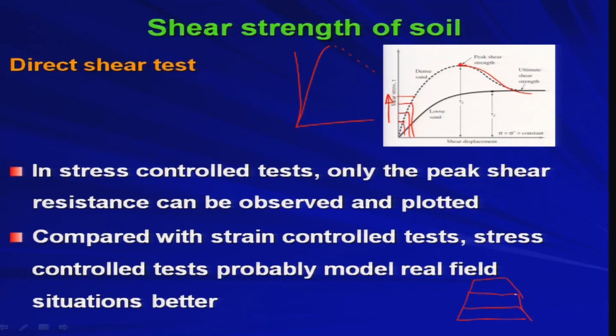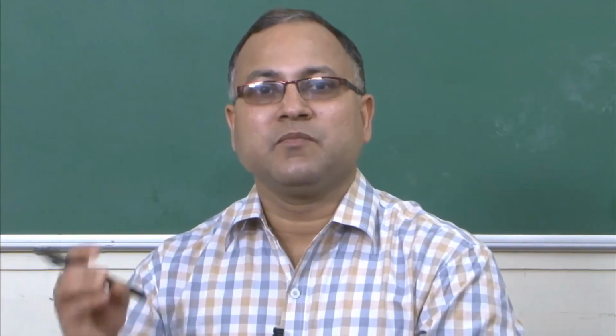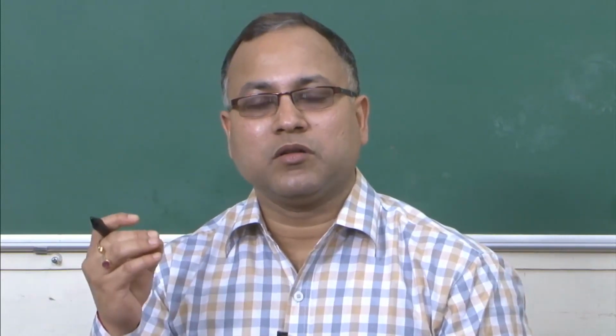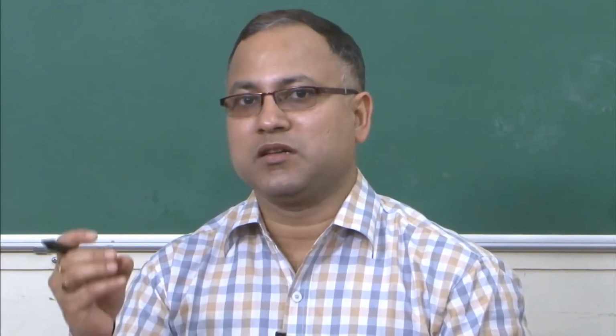In this process of incremental stress, you are controlling the stress in the soil. So the stress control test is more associated with the actual field condition than the strain control test, where you control the displacement. That displacement control is not really happening in the field in actual life.